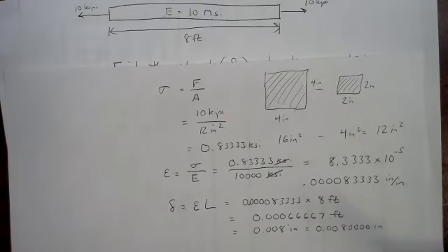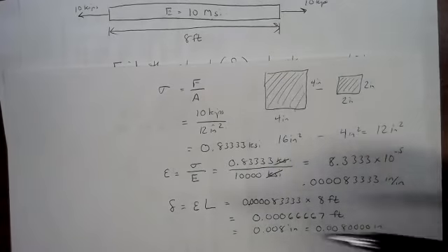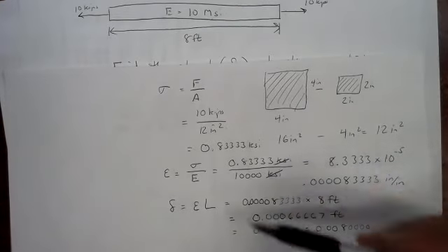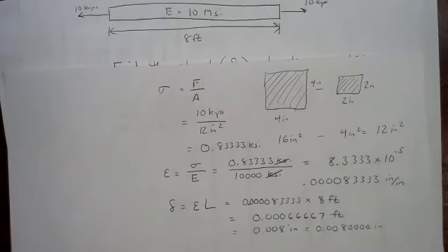So, 4 thin sheets of paper. It's not very much. That means this beam is relatively stiff. It's got low enough stress that it's not really going to change shape all that much. Any questions on that process? All right, let's try another one here.